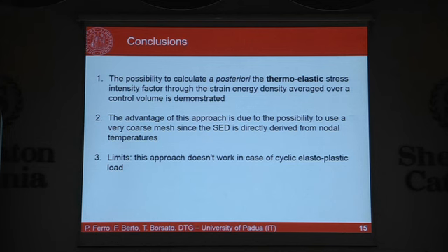And what we can do is calculate the strain energy density by using a coarser mesh and then obtain the correct values of the notch stress intensity factors. There is a limit, in my opinion.